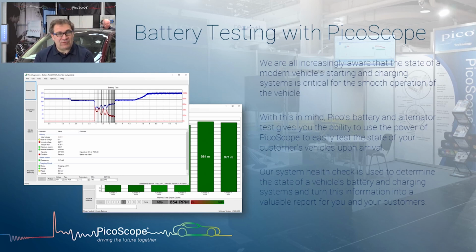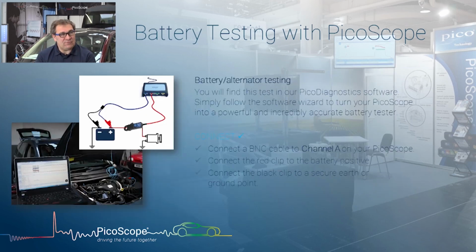So effectively we have the same help in here. We have help files, so it shows you how we connect and how we capture our data. Again, we've got these nice little diagrams. We're going to use 2 channels of PicoScope. Channel A is literally 1 test lead across the positive and negative of the battery. And then we've got our 2000 amp current clamp taken around the battery positive cable coming away from the battery. So that's how we connect it.